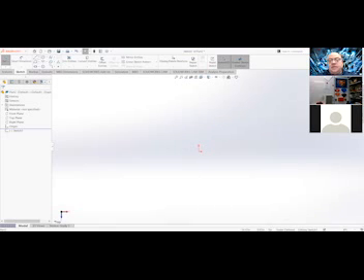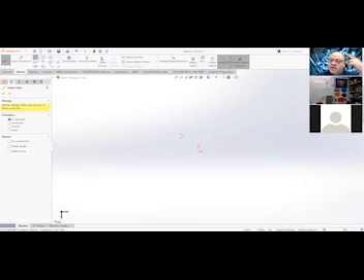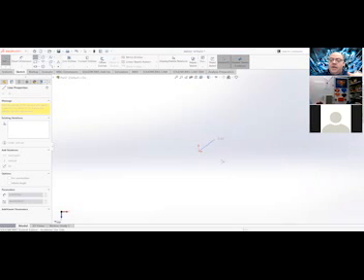Why don't you go up to the line tool, and L is line, just like in AutoCAD. So nothing really new there. So click on the line tool, and notice your cursor is now a pencil. So we're in that mindset of drawing as we go. Bring your cursor down and find that dot. I'm going to start right on the origin point. So when we click on that origin point, we are now, just like in AutoCAD, ready to draw a line.